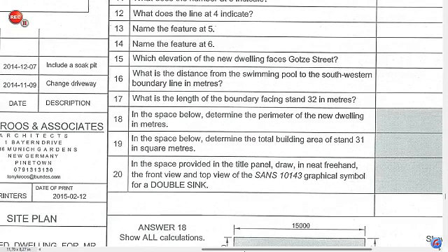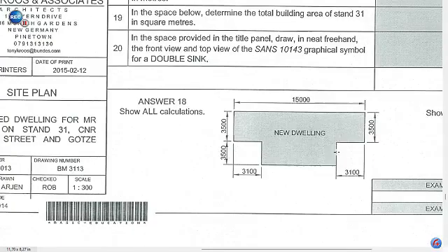I automatically convert the millimeters to meters. This here is 3.1 meter. This has been omitted. This is 3.5 meters up, that is 3.1 meters, and that is going to be 3.5. So we need to determine this distance. Before you can calculate, we will take 15 meters and we will take 3.1 meter plus 3.1 meter, and that will give us 6 meter 200 if we add it and we subtract that from the 15 meters, and that answer will be 8.8 meters, which you will write in here.